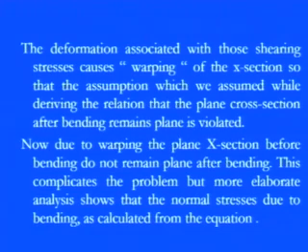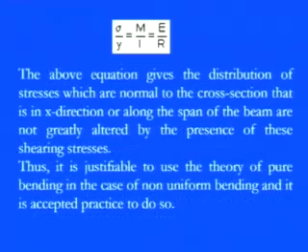This complicates the problem, but a more elaborate analysis shows that the normal stresses due to the bending, as calculated by a simple equation like sigma by y equals M by I equals E by R, which gives the distribution of the stresses normal to the cross section along the span of a beam, are not greatly altered by the presence of these shearing stresses. Thus it is justifiable to use the theory of pure bending in the case of non-uniform bending, and it is accepted in practice also.